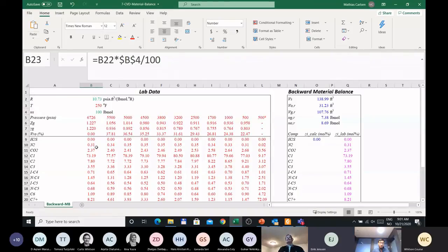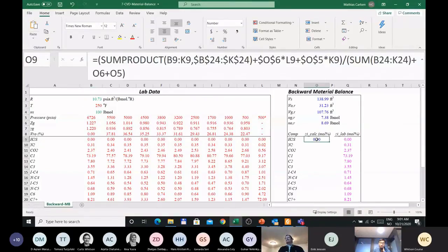Thanks. Yeah. So this 100 moles, we can also start the material balance with, let's say, 1,000 moles or 500 moles. 100 is just a good number to keep things clean. But if you say 1,000 moles, you will see that the material balance will remain the same. All the results will remain the same, the final material balance calculation.